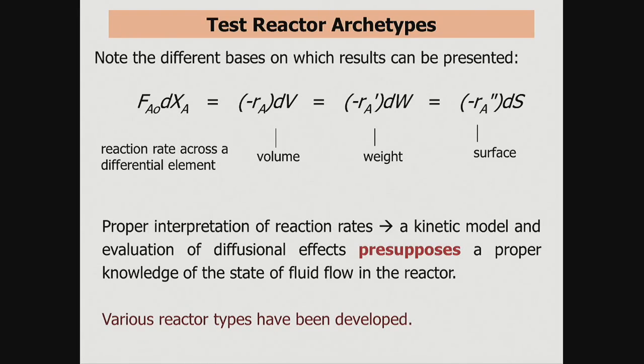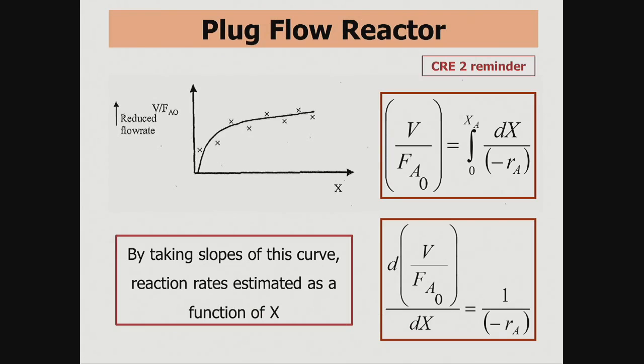So you've got to evaluate a kinetic model, try to figure out if it's diffusional constrained, if it's mass transport limited, or if it's surface reaction limited. You want it to be surface reaction limited because then your model's going to work probably. If it's not, you're going to have a problem. So to help you, various types of tricks have been employed.